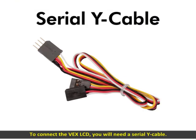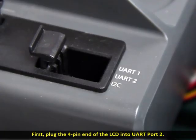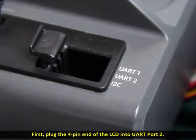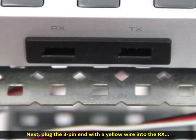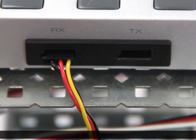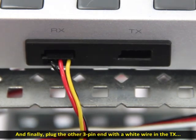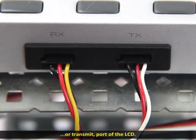To connect the VEX LCD, you will need a serial Y cable. First, plug the 4-pin end of the LCD into UART port 2. Next, plug the 3-pin end with a yellow wire into the RX, or receive port of the LCD. And finally, plug the other 3-pin end with a white wire in the TX, or transmit port of the LCD.